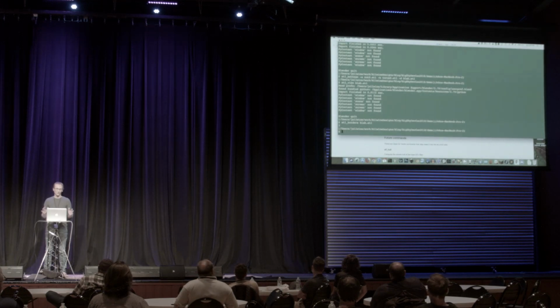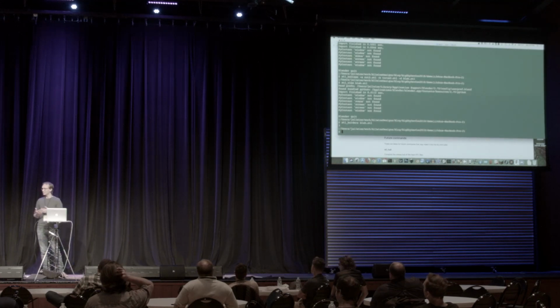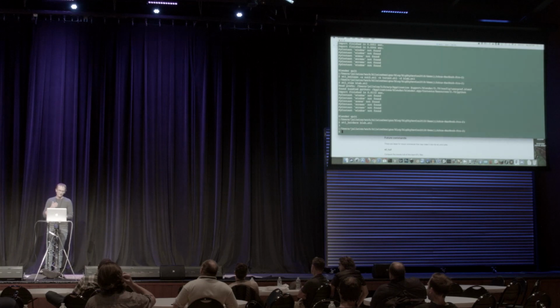blah.stl. Ooh, 3. Okay, so the way STL Boolean works is it takes a model and creates a binary space partition where it starts slicing the model up based on arbitrary planes it finds in the model. And it will keep splitting until it has this tree all built out.